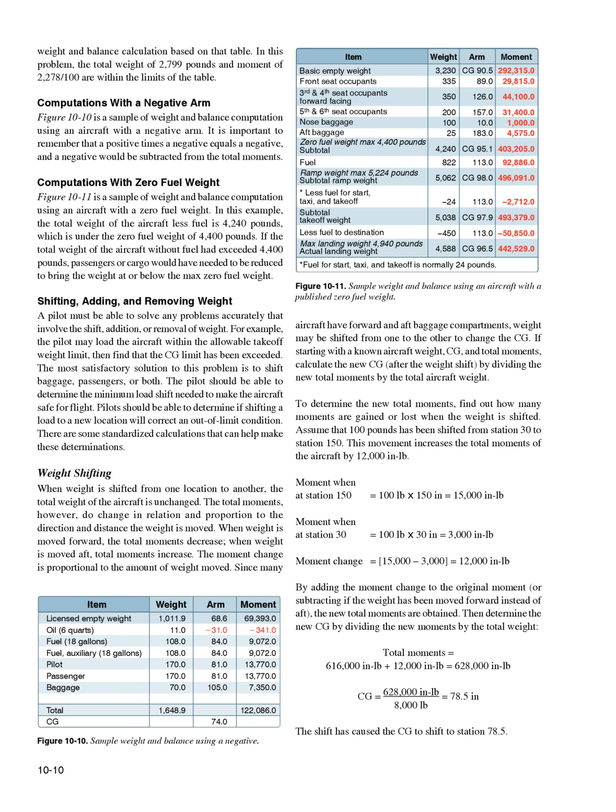Weight and balance calculation based on that table. In this problem, the total weight of 2,799 pounds and moment of 278/100ths are within the limits of the table. Computations with a negative arm. Figure 10.10 is a sample of weight and balance computation using an aircraft with a negative arm.